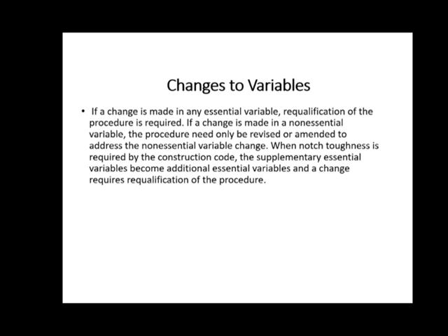So what's that telling us? That's telling us that if we change something that's a non-essential variable on the WPS, we can change it, and we just have to revise the WPS to reflect that we've changed that variable. If it's an essential variable and we change it, then we have to requalify the weld procedure.